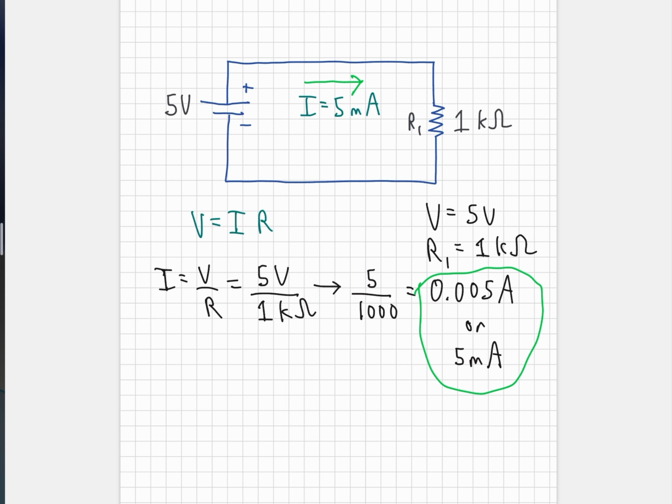The formula is P equals I squared R. That means power equals the current squared, multiplied by the resistance. That is the formula that you use anytime you see a resistor. You'll always use this formula right here. So let's plug in our values now. Power equals, we'll use the amps for the current and not the milliamps.